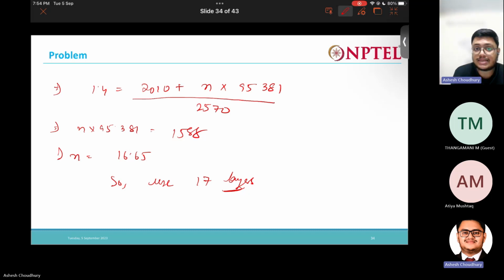Whereas the other researcher, Schmertmann et al., gave methods and charts where the lengths reduce with height, similar to what we saw in the case of reinforced earth walls. He varied the length of the reinforcement with the height of the slope. All right.